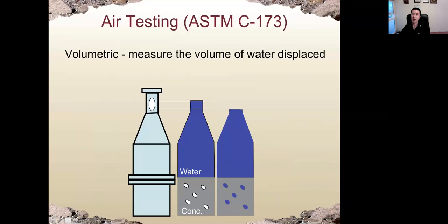Sometimes we also need to measure the air content in concrete. Air content is important because it will affect the strength of concrete, the workability, and also the resistance of concrete to freeze damage.